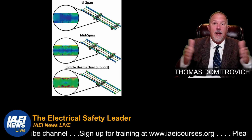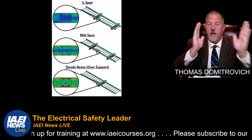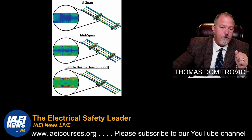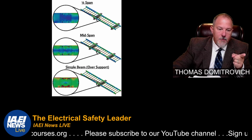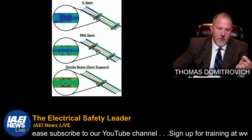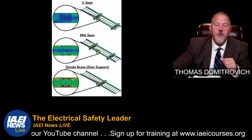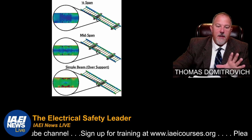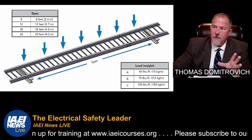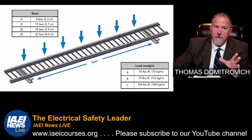I personally like a little bit of overhang, and I like to keep the splice in between the supports on either side of the splice. Only one cable tray splice plate should be placed between support spans, matching the tray length, etc. Right? So you've got to think about your supports. You've got to think about the weight that is going to be placed on your cable tray.